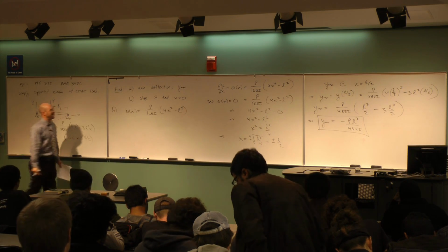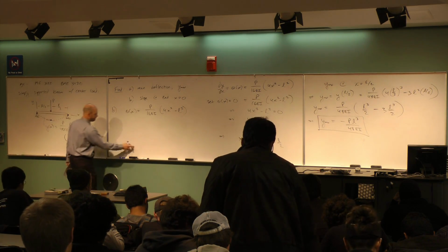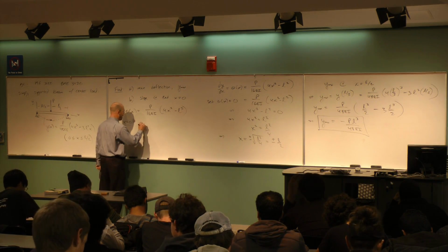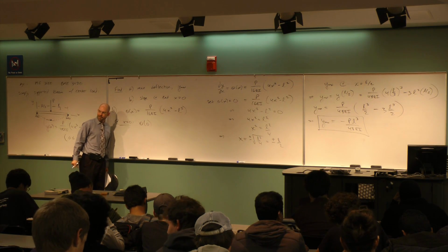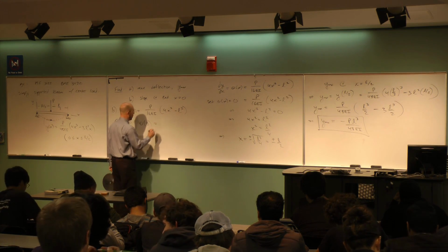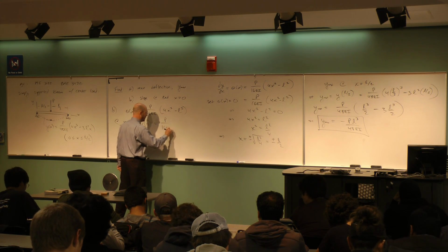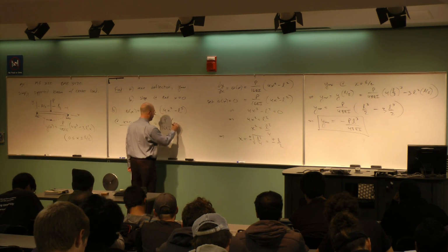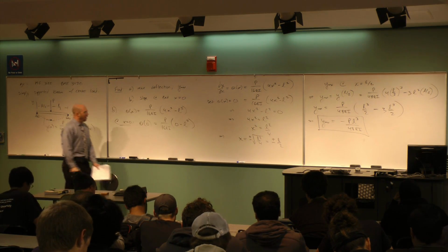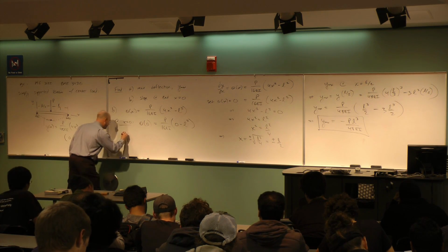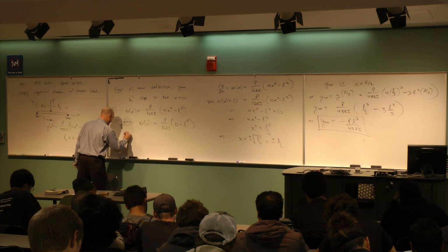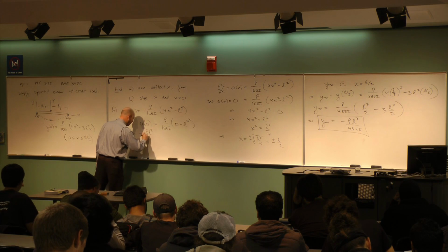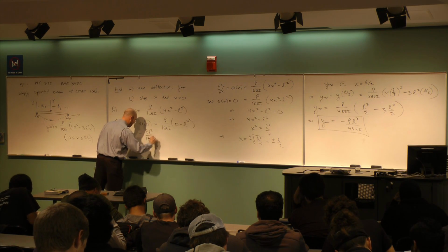So if I want the slope at the end, x equals 0, what do I do? Yeah, I evaluate this at x equals 0, right? So I want theta of 0, not theta multiplied by 0. Theta evaluated at 0 gives me P divided by 16 EI, and I put a 0 wherever the x is, right? So it's 0 minus L squared. So theta evaluated at the left end, theta of 0, is going to be minus PL squared divided by 16 EI.